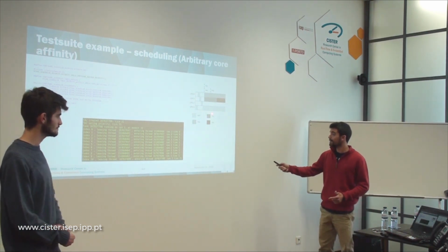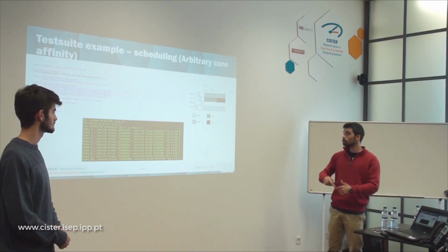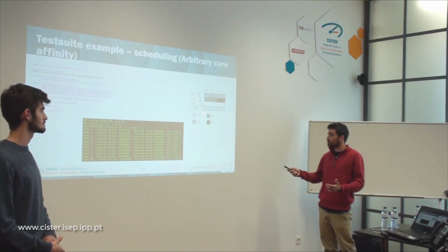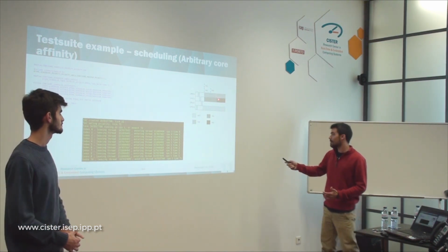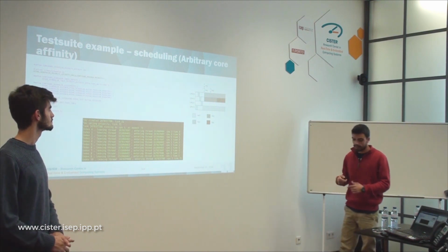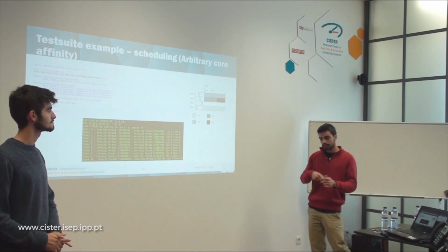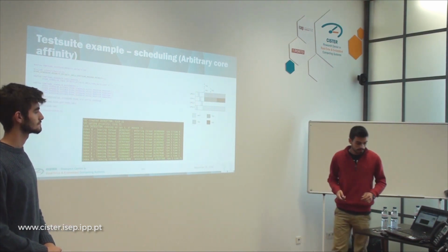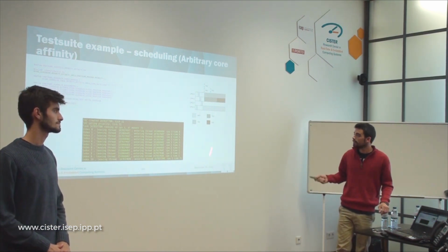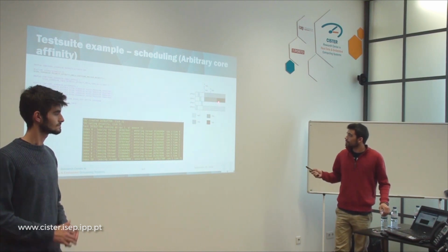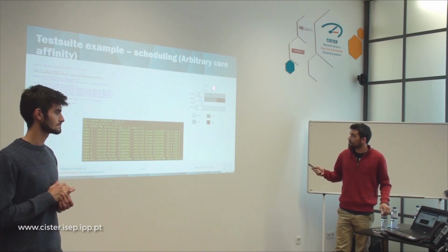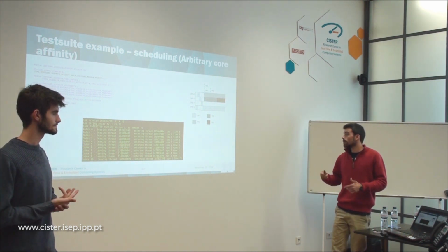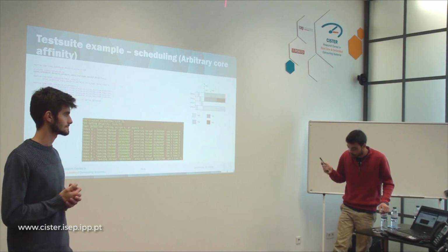Lastly, we have here the init task. The init task is a non-preemptive task, so we already can forget processor 3. It won't enter processor 3. So our two main options were to set its priority with a directive offered by the task manager of RTEMS, that is rtems_task_set_priority, and we've done it, to later, at that moment, set its priority to finally preempt either CPU 0 or to enter either CPU 0 or CPU 1.